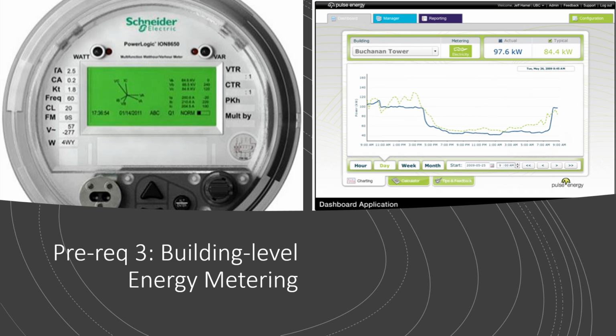The third prereq is building level energy metering. The intent of this prereq is to use energy metering to identify opportunities for additional energy savings by tracking building level energy use. Projects need to install new or use existing building level energy meters, or some meters that can be combined to provide total building energy consumption, like electricity, natural gas, chilled water, steam, fuel oil, propane, biomass, etc.